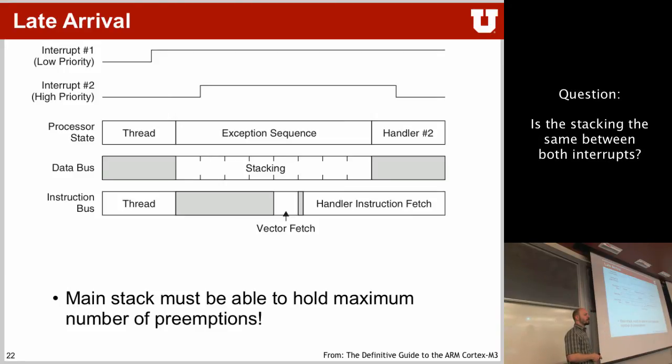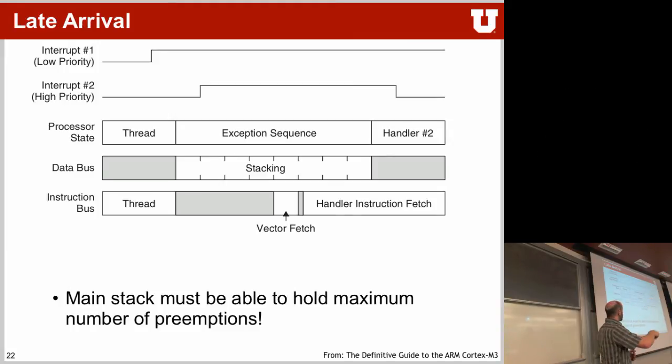So it does finish stacking from the first step, or it's the second? It's the same thing, right? Because the stacking takes the main program and puts it onto the stack. There's nothing it has to go and fetch for the interrupt service routines, except the location. And as long as this vector fetch here hasn't happened yet, it will fetch the one of the higher priority.